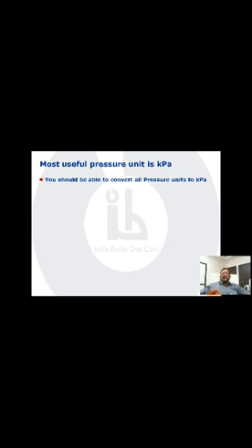And you memorize. Whatever you write down in the reference, you memorize. That is going to help you a lot. So starting with kPa, kilopascal: the relation between bar and kilopascal, 1 bar is equal to 100 kilopascal. And in fact, when you try to convert the pressure units, I would suggest that you convert it through bar. You come via bar. For example, let us say 1 kg per centimeter square. You convert into bar.